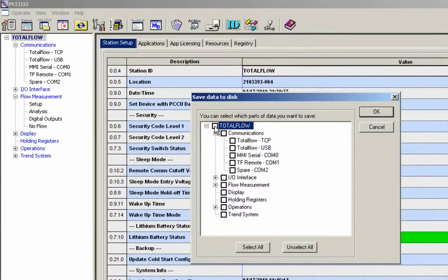What I use this for a lot of times is when I set up a communication port, and there are a lot of tedious things you need to turn on, like parity and your stop bits and so forth. A lot of times people will ask, how did you set up your COM1 on your G4?